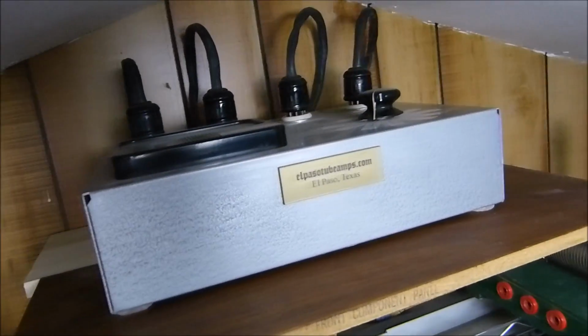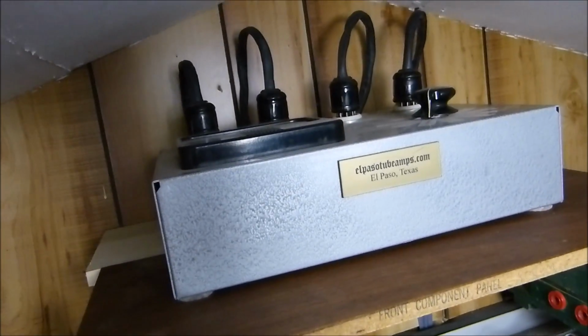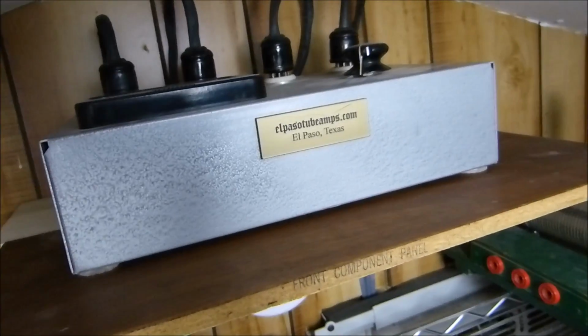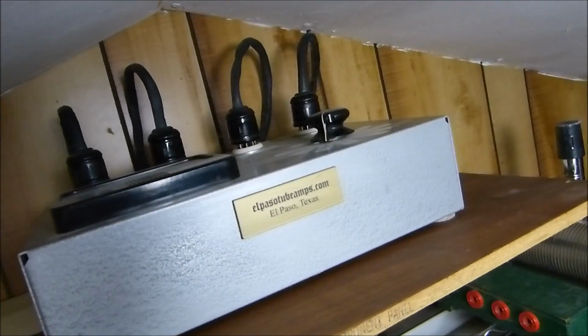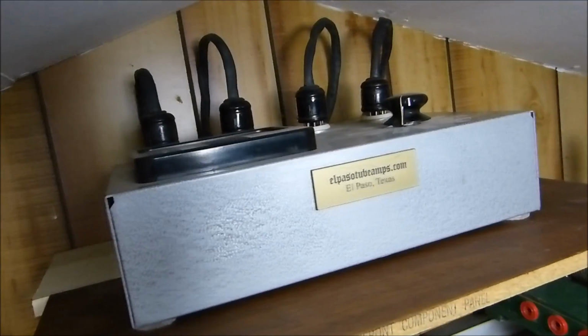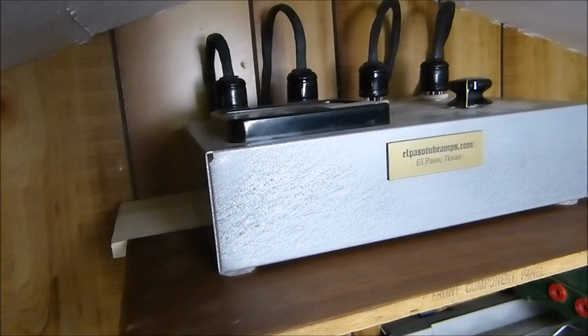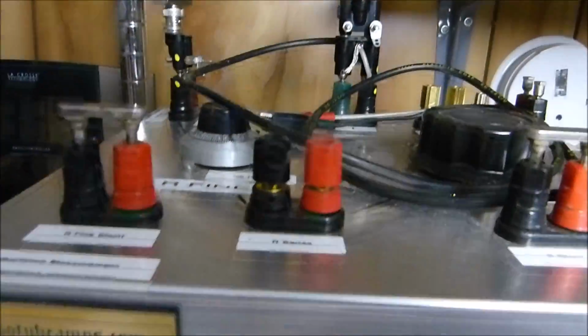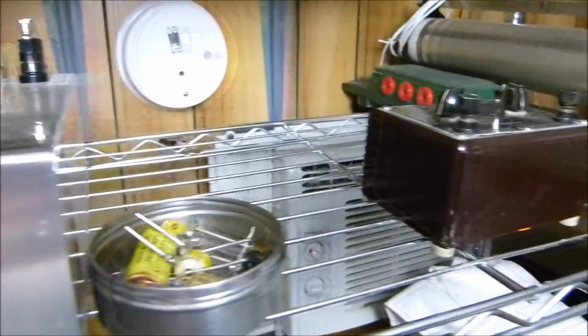Right there's a plug, a device that I can measure the plate and the screen current of 4 tubes at a time. You just unplug those cables from the sockets they're plugged in and plug them into the amplifier where the tubes would normally go, and plug the tubes into this device. Now these are the kinds of things that I figure people are interested in.